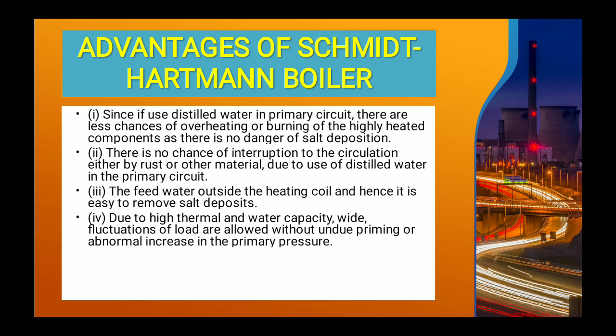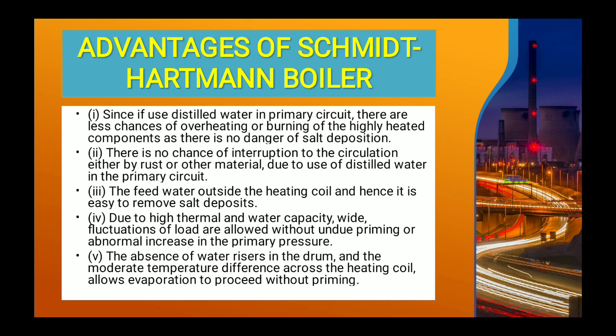Due to high thermal and water capacity, wide fluctuations of load are allowed without undue priming or abnormal increase in the primary pressure. The last one is the absence of water riser in the drum, and the moderate temperature difference across the heating coil allows evaporation to proceed without priming.